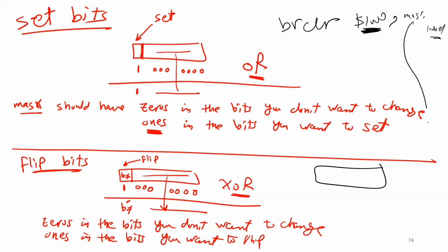In this mask, I told you the way you have to do the mask is the bits you want to branch, if they are clear, you have to put 1 in the location of these bits, and then you have to put 0 everywhere. Is that okay? That's what I explained before. If you do it this way, I'm going to branch to this location if this bit is 1. And that's what you should do in tomorrow's lab. Okay, tomorrow's lab you need to do something like that.